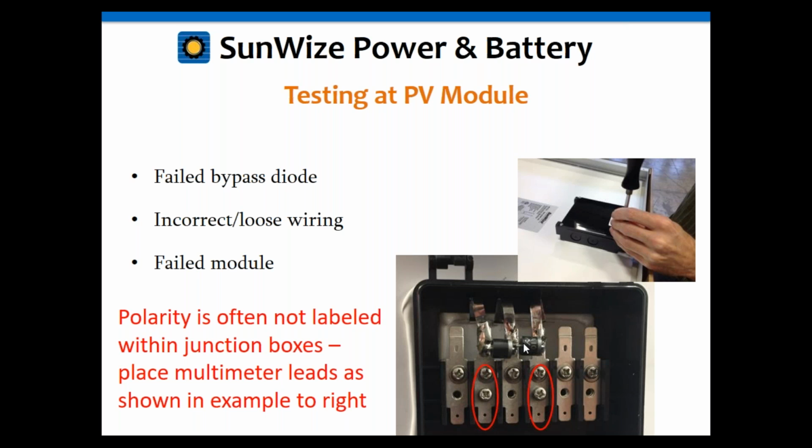Also, the diodes, looking at this, these are soldered, so I don't worry about them so much, but if you have ones that are installed mechanically with a screw terminal, something like that, they could accidentally be installed backwards, they could be shorted, or they could be failed open. So that's something else you could spot here by going through that. I'm going to go into more detail on what the values are that you're looking for that tell you what might be going wrong.